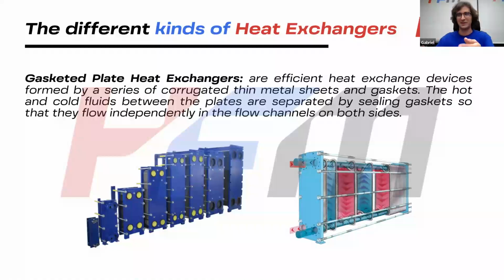And here you can see the pictures. And here in my hand, you have a miniature of the heat exchanger. For sure, some of these devices are even bigger than myself. Here's just a miniature so that you can understand how it works. You can follow up with the drawing as well. One of the fluids enters here and goes out from this other door, and the other fluid in the opposite direction enters here and goes out of the other door. And here we can see the series of the corrugated plates with the gaskets.